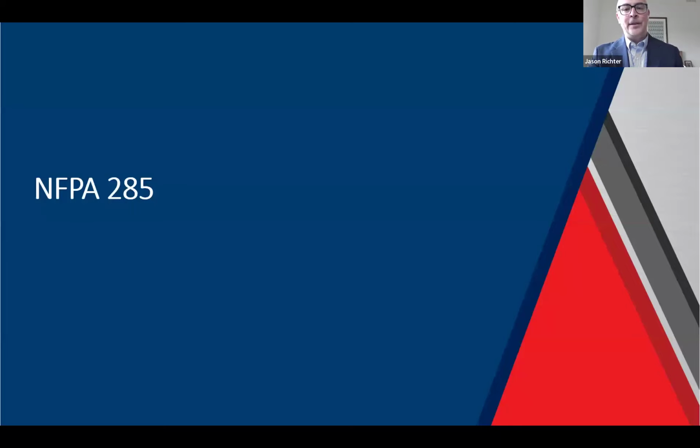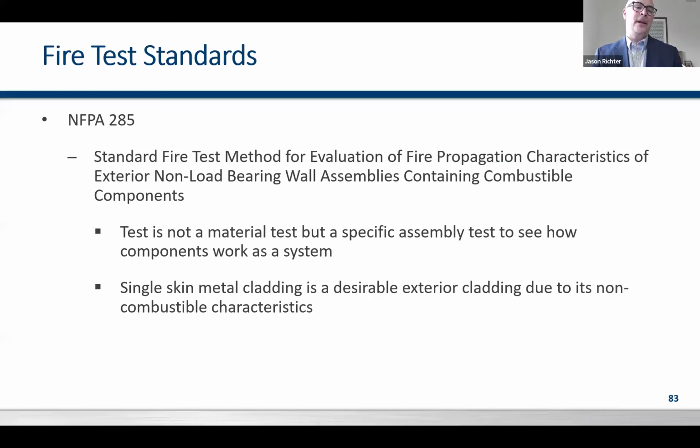Another thing that you have to deal with in rainscreen design is NFPA 285. It's a standard for fire testing methods. Again, no assembly that I'm aware of is specifically tested to this, like with the voluntary AAMA test for drained and back vented and pressure equalized rainscreens, you have a variety of different manufacturers in there.